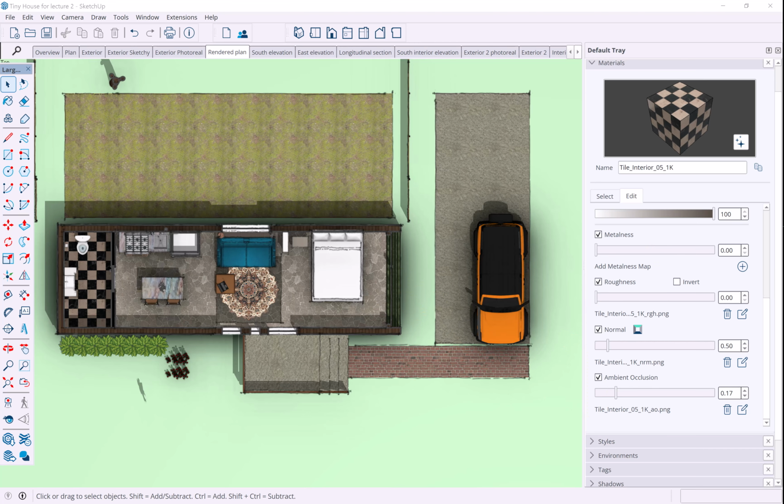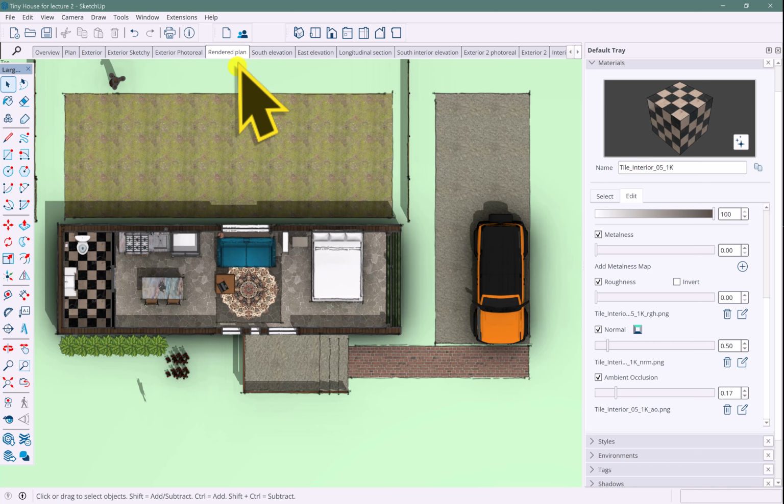A nice little feature integrated with SketchUp is the ability to share your model so that you can get comments from other people. This is because there is a feature called Trimble Connect that allows you to upload models and have other people share them. And then there's a little comment button that you can use to add comments to parts of your drawing. Say, I don't like the way your furniture is laid out, or whatever it is.